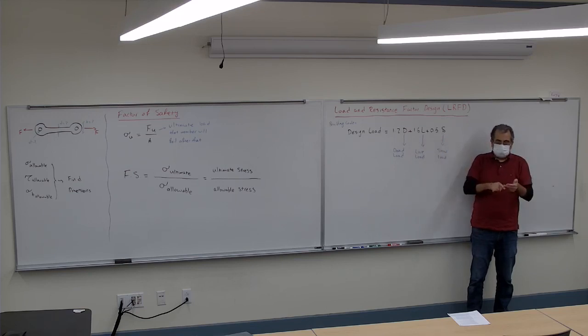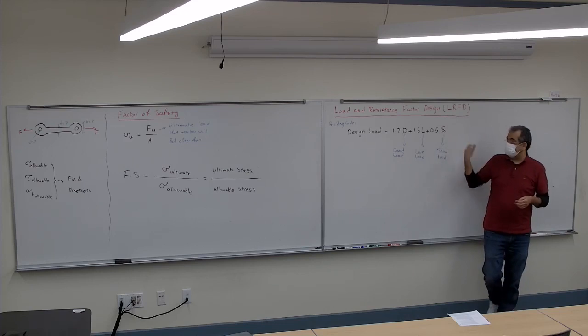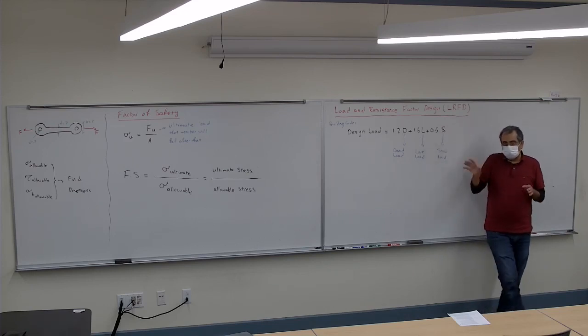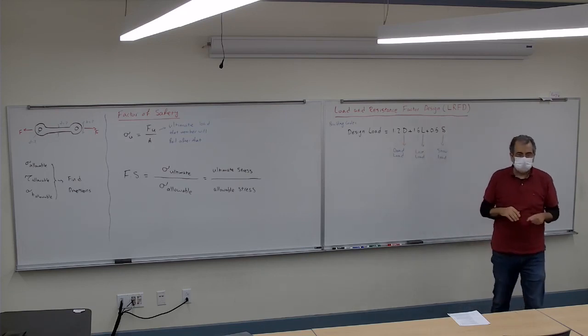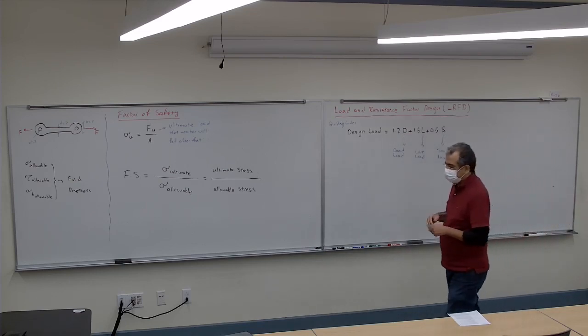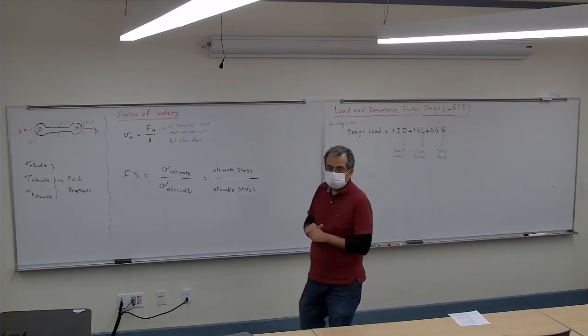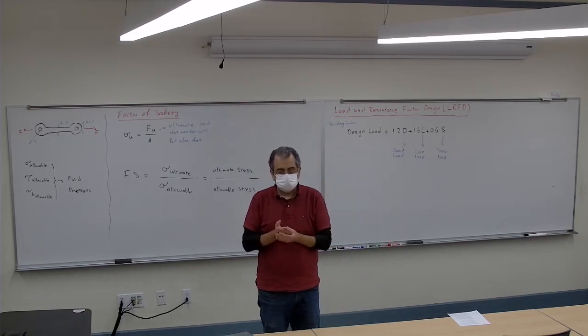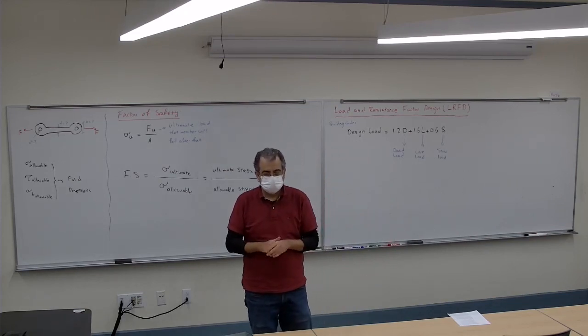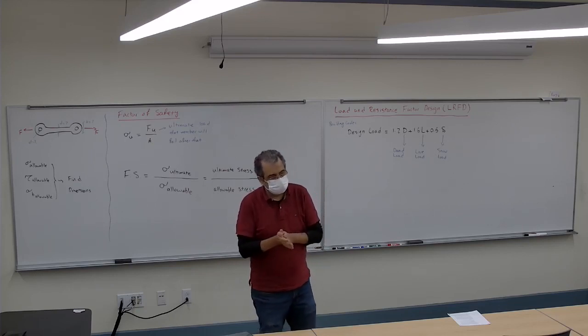It is very unlikely for these three to happen at the same time. So that's why you still want to consider the snow load, you don't want to ignore it, but you don't want to way over design, because usually that is never going to happen, all of that at the same time. Yeah, the Vikings' old football field, they probably did only 0.5 snow load, and their dome part of it collapsed. Yeah.